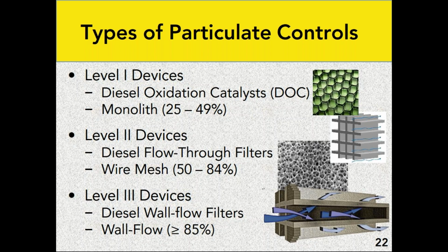If a channel is plugged on the intake side, it will be open on the other side of the device. If it's open on the intake side, it will be plugged on the exhaust side. That's difference number one. Now, these plugs are impermeable, by the way. Difference number two is that the ceramic material that the sidewalls are made of has been treated much like you would treat activated carbon.